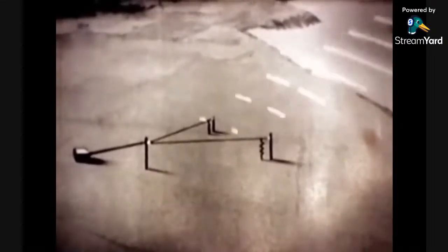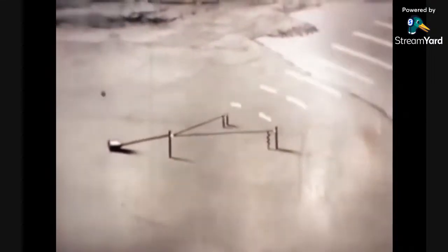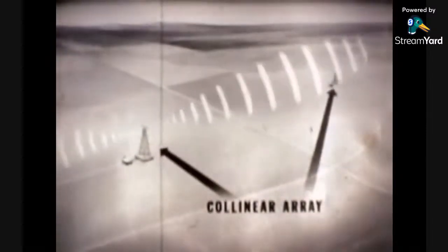Now then, to reach the desired transoceanic point, this wave pattern is projected toward the sky, where it hits the ionosphere. So, the main job of the long wire or V antenna is to beam as much energy as possible into the sky at an angle so that the beam can be returned to the Earth at the desired point of reception. As you remember, while the collinear array antenna is basic for short distances, the long wire and the V are also considered basic for transoceanic communications.